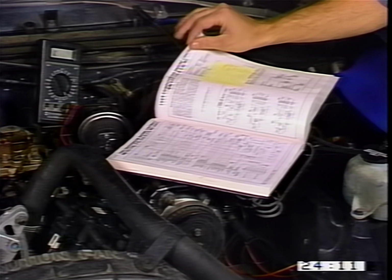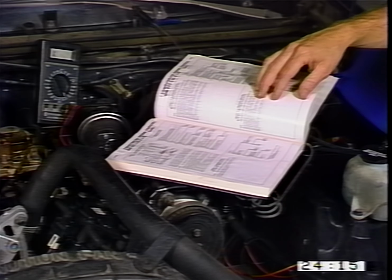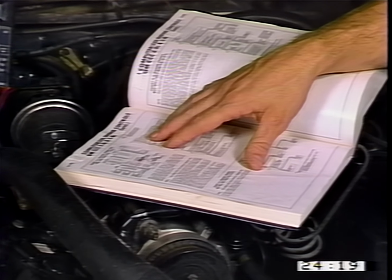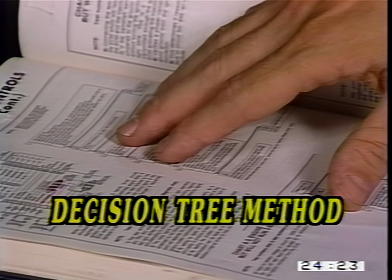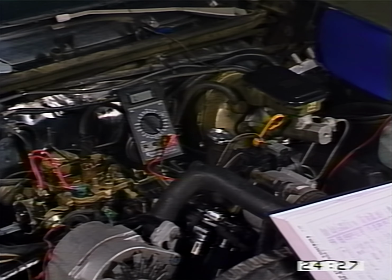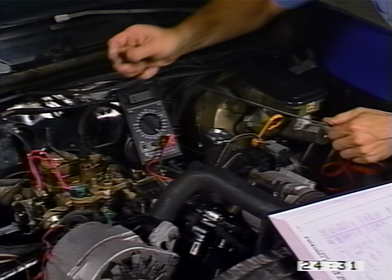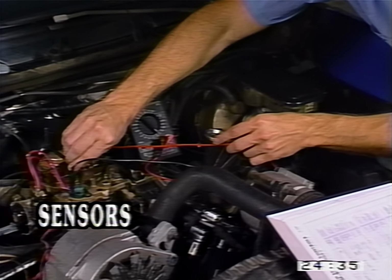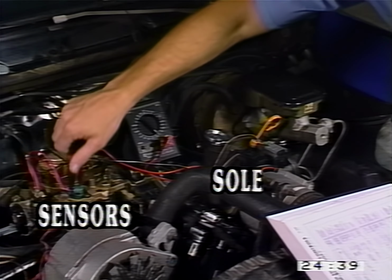Servicing computer-managed vehicle engine systems involves eliminating all possible causes besides the computer first. If all the components check out, then the computer is tested. This is termed the decision tree method of system diagnosis. The components and systems which are tested in eliminating trouble prior to diagnosing the computer and its PROM are the sensors. They are checked to see if they open and close and if their resistance values are to specs.